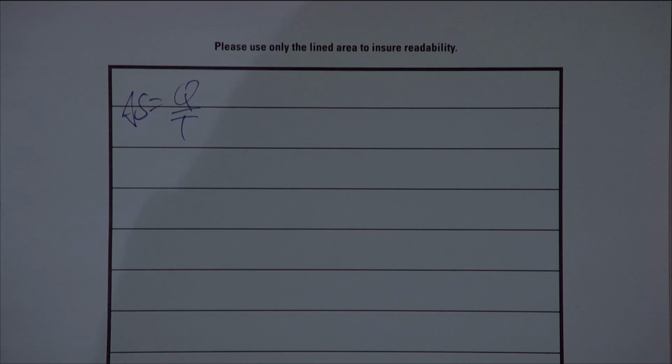However, for most of the problems, you would just use the entropy data that exists within the property tables. If you knew that you had a particular process between some point 1 and some point 2, you would just look up the entropy at state points 1 and 2. Or if we had something like an ideal gas or a solid or a liquid, you would use the equation that includes a natural log of the temperature ratio and perhaps some other terms. But you'd use that for those types of problems.